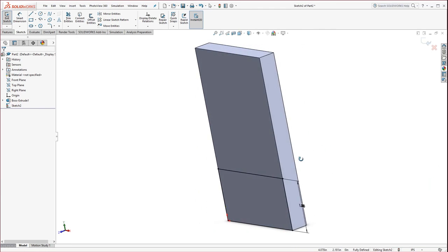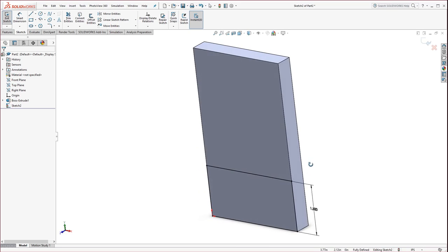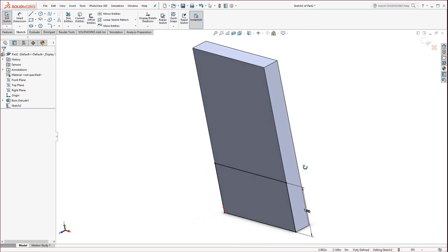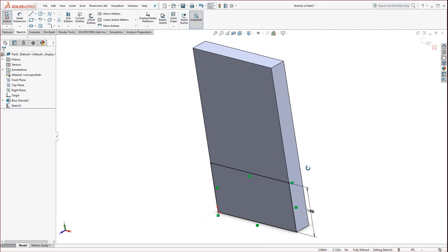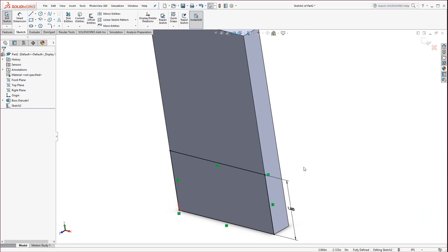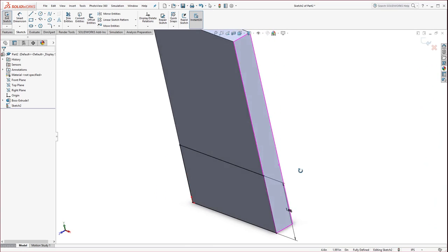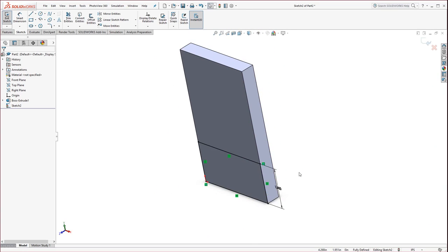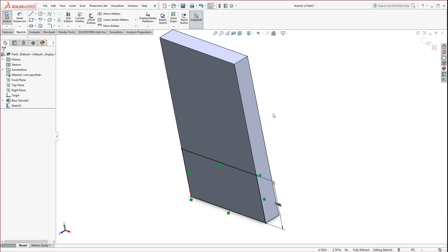And if we rotate around, remember the mouse button you rotate around with is the center mouse button, which is typically a wheel these days. And you're not actually scrolling that center mouse button. If you want, that zooms in and out. You're just holding it down and moving left and right, up and down to rotate. I would recommend, if you want, pause this video and play with it for 15 minutes. Rotate, hit your space bar, go to the different views.